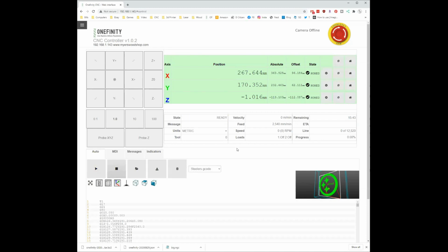Holding user stop. I'm going to go turn the router off. And that's it. So there's no way to start it up again from that spot unless you knew how to edit G-code and find whatever G-code you were at and delete the beginning parts, and then it'll start right where you left off. I've never done that in the four years I've had a CNC, and hopefully you never have to. But yeah, that's it. That's all I know to show you, unless you have any other questions.